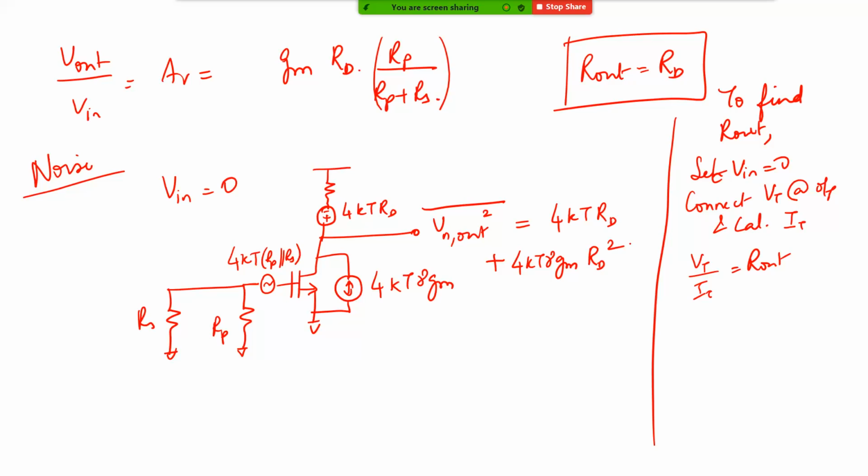Here the transfer function is the resistance. You have a certain amount of current being pulled from the output, and you calculate the output impedance. The MOSFET current into Rd is the voltage, but for the power spectral density, you take the current power spectral density multiplied by Rout squared. That's how you get 4kT gamma gm Rd squared.